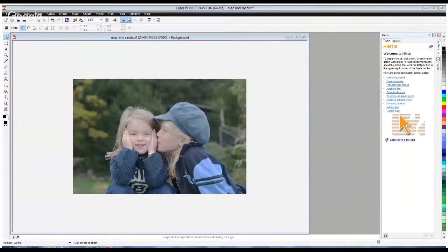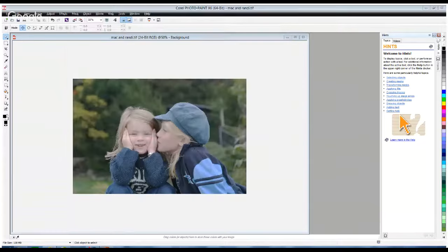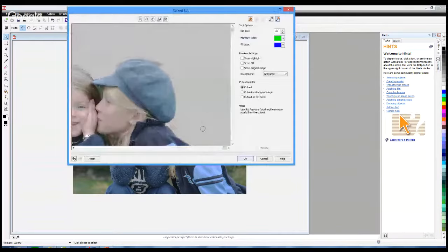And you can see that there's some information here that we need to get rid of, because if I bring this into the software to engrave it, I may start to get the halo around the outside here. So that's again very easy. We're going to click the remove detail button. I'm going to just click on here, hold the left mouse button down, get rid of this right here, let go of the mouse, and I'm going to go through this fairly quickly and get rid of this excess background here.